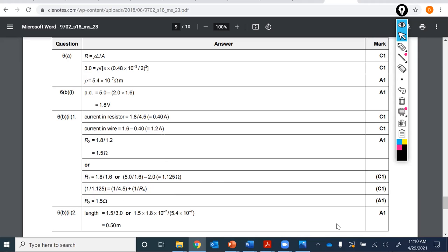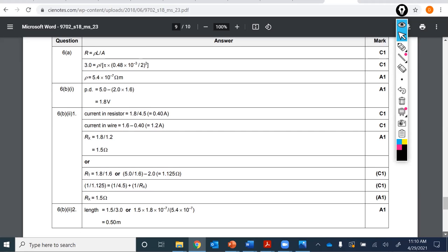So again, you get sort of the same. I think here they're using the actual resistor equation, saying 1 over the circuit resistance equals 1 over R1 plus 1 over Rx. So here they've calculated the total circuit resistance, and then they're using the equation for summing resistors in parallel, summing the reciprocals, and they've solved it for X there. So they've solved for that unknown. But you can see that, in my opinion, this way is a bit more clear, straightforward. It's good to see how both ways work though.